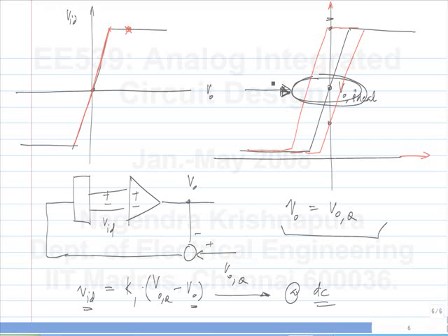So you have feedback around the op-amp to get the desired signal processing function, but for a real op-amp to behave roughly like an ideal op-amp, you need to have DC negative feedback also. Okay? So whatever feedback network you put to realize your signal processing function must also provide DC negative feedback around the op-amp so that it gets biased decently. Okay? Is this okay?